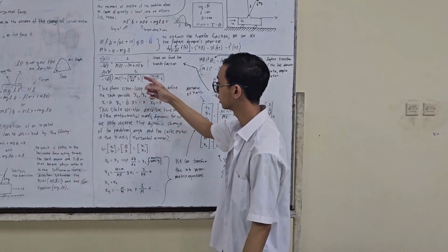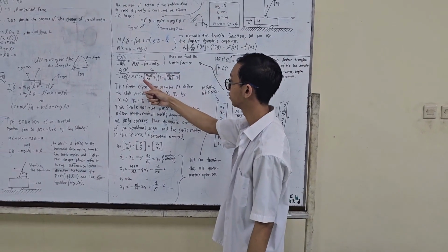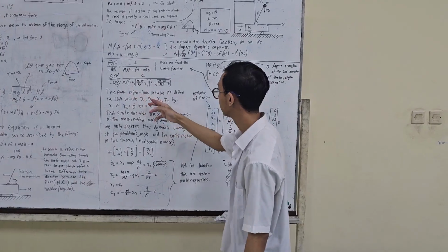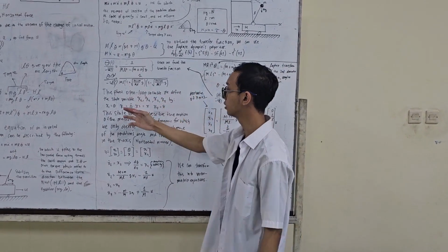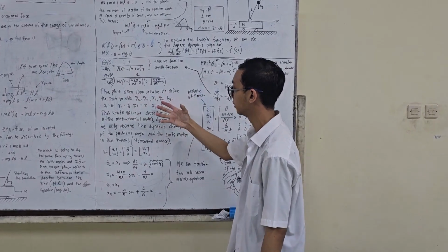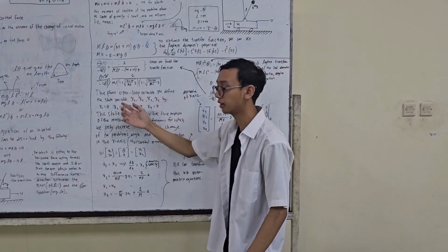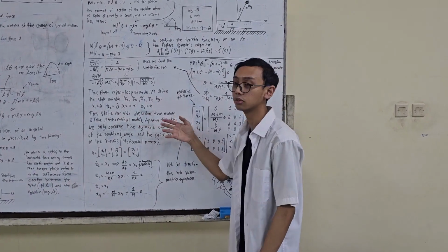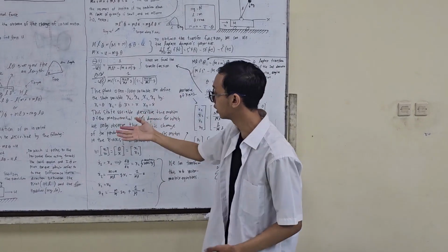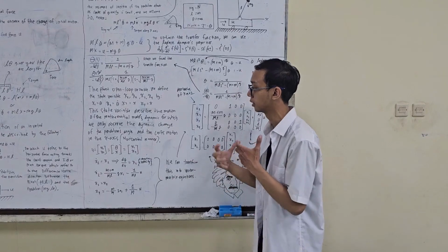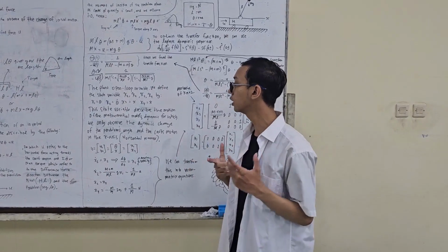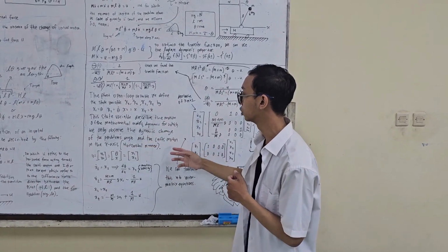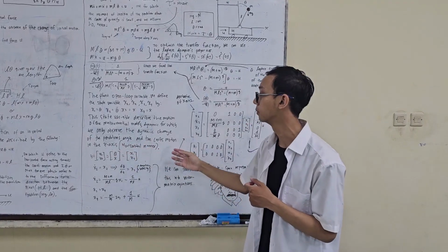And if we see here, there's a positive real axis pole and a negative real axis pole, which means this loop is unstable. And we define the state variables x1, x2, x3, and x4 by x1 being theta, x2 equals theta dot, x3 equals x, and x4 equals x dot. This state variable describes the dynamics of the mathematical model, for which we only observe the dynamic change of the pendulum's angle and the cart's motion along the x-axis, the horizontal direction.